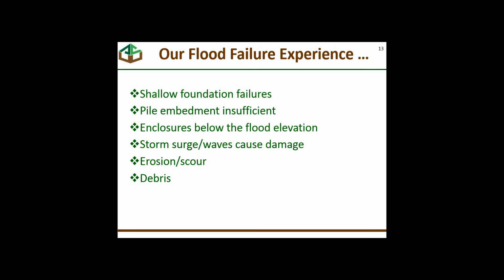We certainly get storm surge and waves that cause a lot of damage, and as soon as the waves start to crash into the wall of the building, most buildings will fail. If we can get the building high enough to have storm surge and waves just go under the foundation, under the floor system, then the building will generally make out fine.